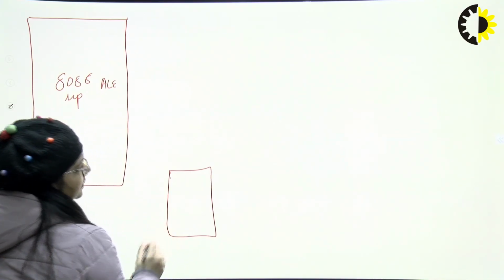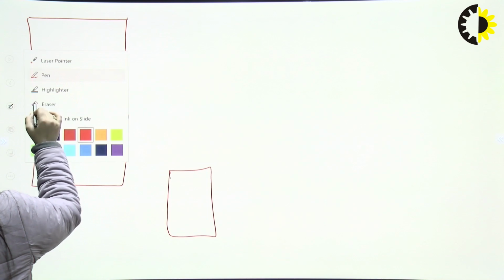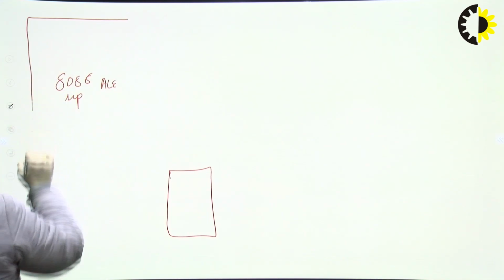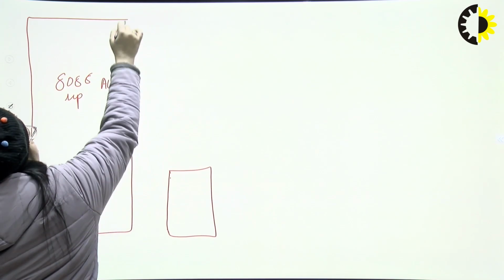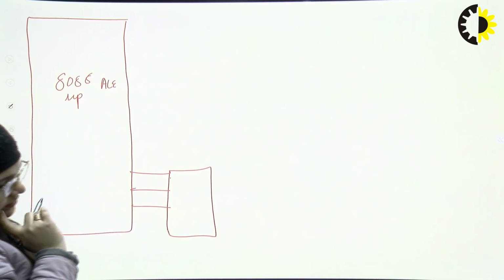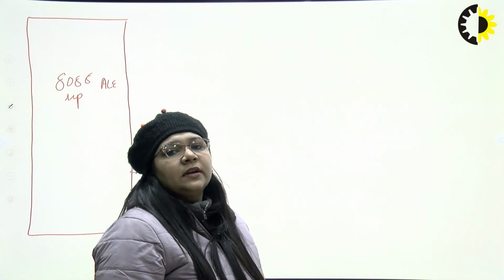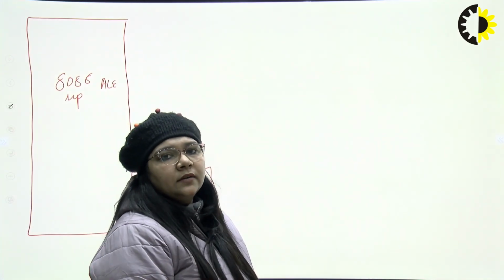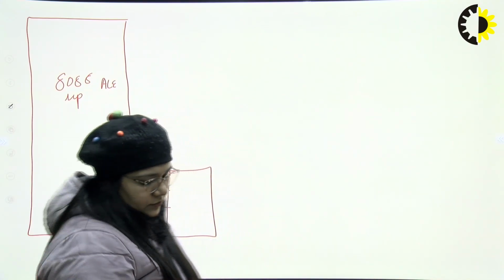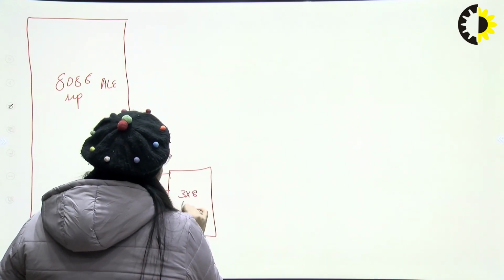Here is the decoder. And next thing is my inputs for the decoder. So the input for the decoder can be the signals. Three inputs for the decoder, that is read and write signals. So read and write signals will be used for decoding these particular signals, for read signal and for write signal as well. So here this is my 3:8 decoder.